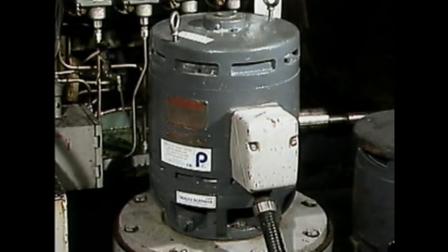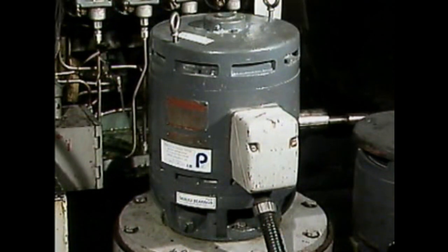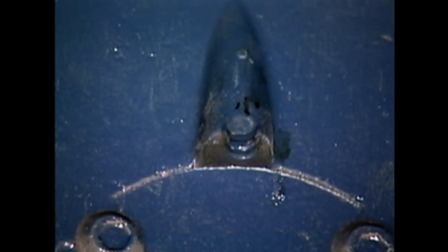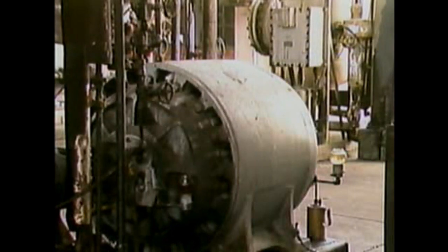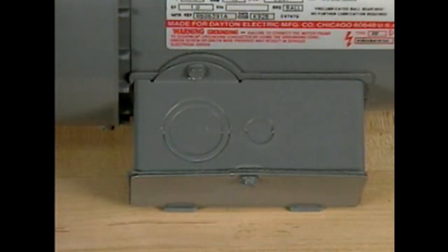There are some motors that use sealed bearings that do not have to be relubricated for the life of the motor. The bearings of some other motors are greased through grease fittings as part of a regular maintenance schedule. Other motors use a constant level oiler. A constant level oiler holds a small supply of oil that drains by gravity into the bearing. The design of the constant level oiler allows the operator to look at the level in the reservoir and add more oil when necessary. A connection box on this motor protects the motor's wires or leads from damage.